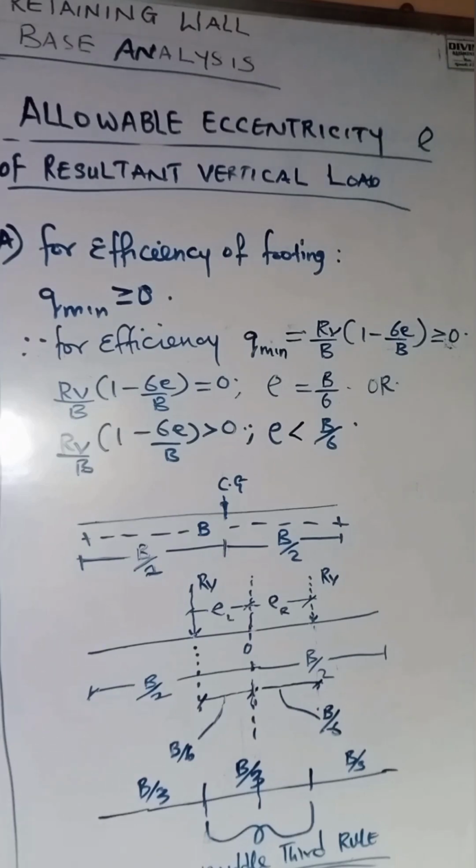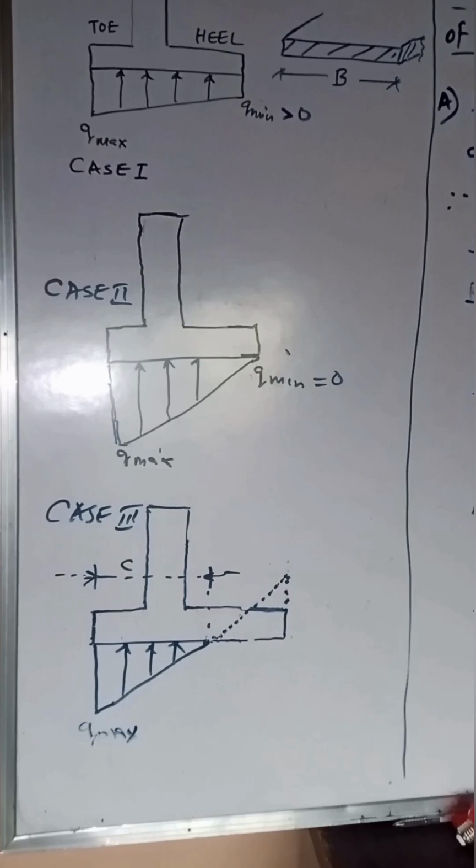So we are going to look at the third case, which is case 3. Now in case 3, we have lost pressure. Of course, for this same structure to still stand and remain stable under equilibrium, the total resultant vertical load that is coming on the soil must be equal to the base reactive load that is going up under equilibrium.